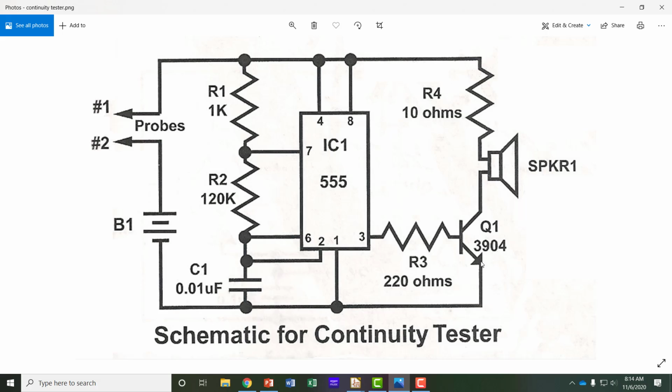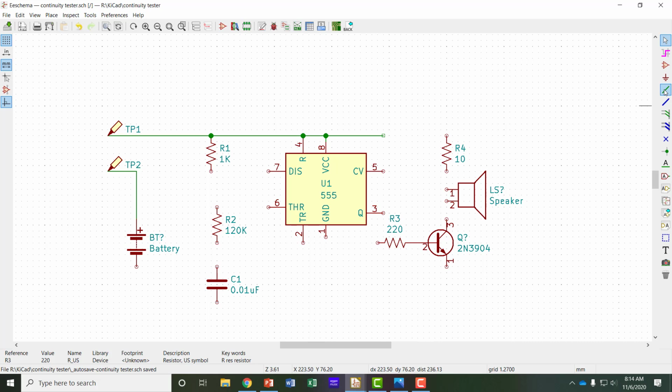Now the emitter of the transistor is connected to pin 1, which is then connected to a capacitor. So I'll go place a wire again, click on place wire. I'm going to go from my emitter, let's drag it over and connect to the capacitor. So I'll double click to end the wire there. Then I'm going to select my cursor again, move this resistor out of the way, select and move my capacitor. I'll connect it right there. And then I also need a wire to connect to pin 1, so of the 555 timer.